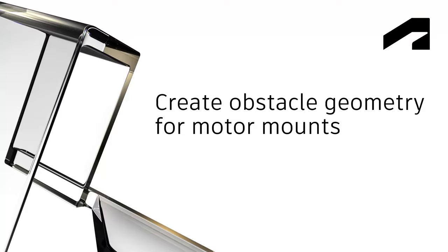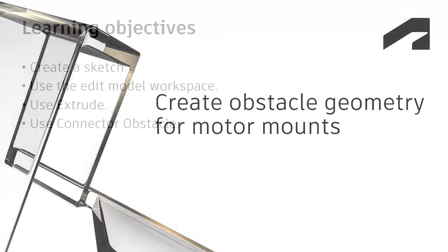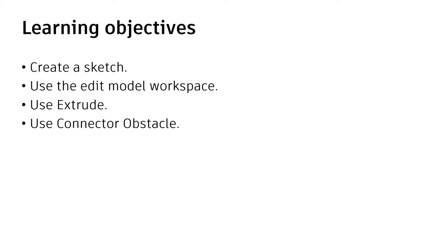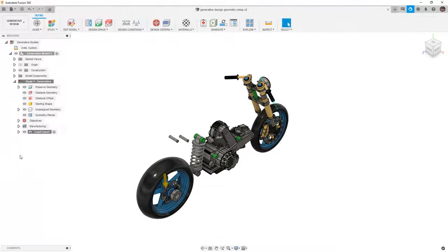Create obstacle geometry for motor mounts. In this video, we'll create a sketch, we'll use the Edit Model workspace, we'll use Extrude, and we'll use Connector Obstacle. In Fusion 360, we want to carry on with our generative design geometry setup.